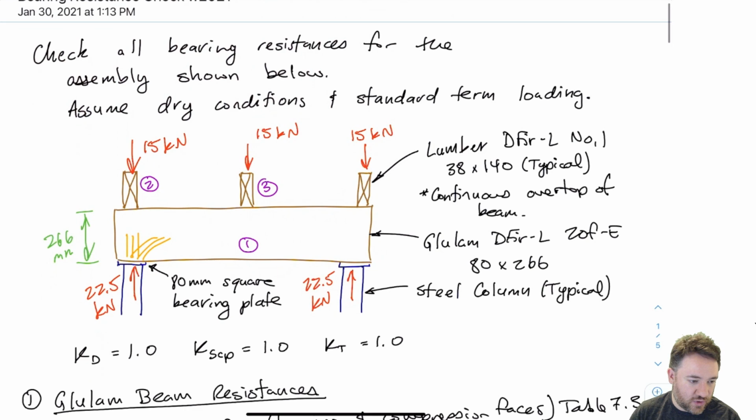So this is the same joist. It's 38 millimeters wide. So really there should potentially be a KB factor because it's a short bearing length. But does it satisfy both categories? One, is it within 75 millimeters from the end of either of the beam? Okay, it's not. It's near the middle, so I think we can safely say that that's not the case.